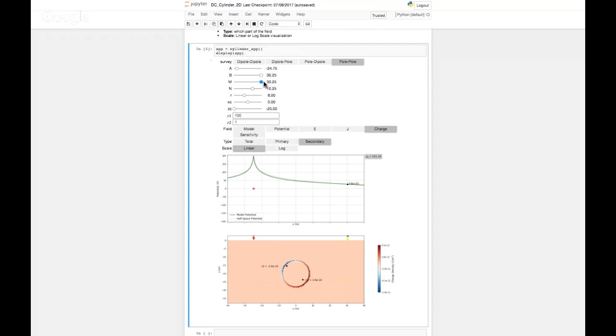Over here is the strongest part of the negative charges up close to the surface. So if I'm any place in here, I'm going to have a decrease in potential. If I'm sitting up here, my apparent resistivity is 90 ohm meters, simply because I'm closest to these negative charges.